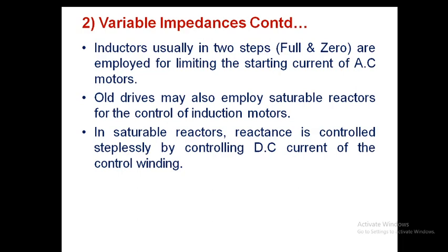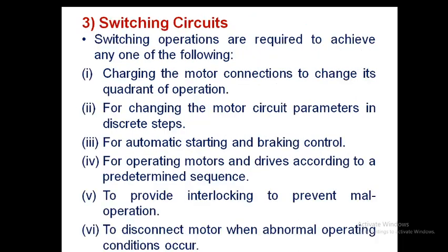Old drives may also employ saturable reactors for the control of induction motors. Saturable reactors or inductors are connected to limit the induction motor starting currents. In saturable reactors, reactance is controlled steplessly by controlling the DC current of the control winding. So that's what we will do with these variable impedances.